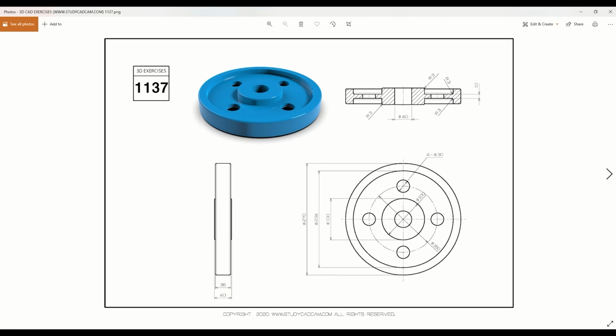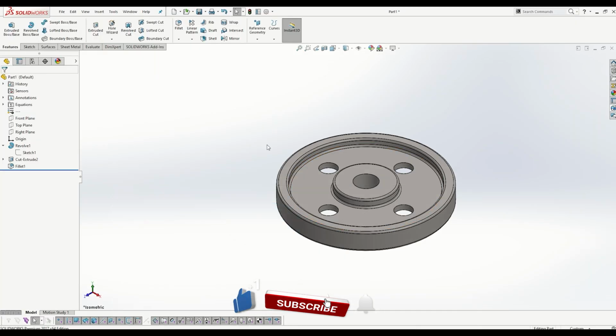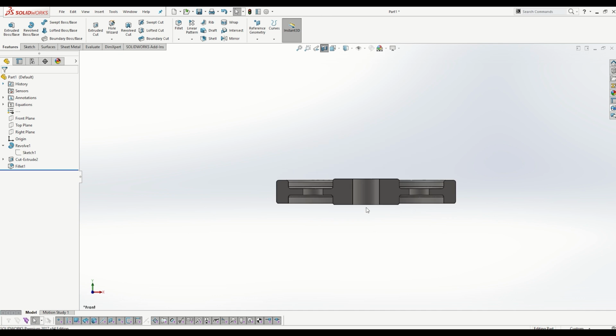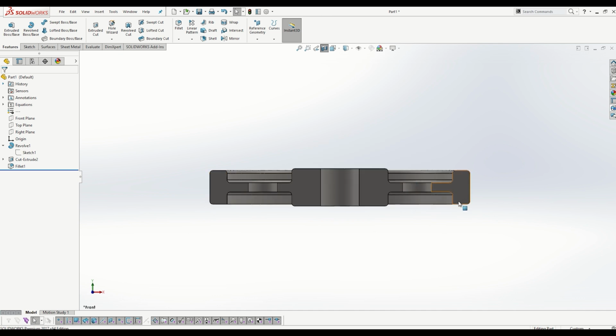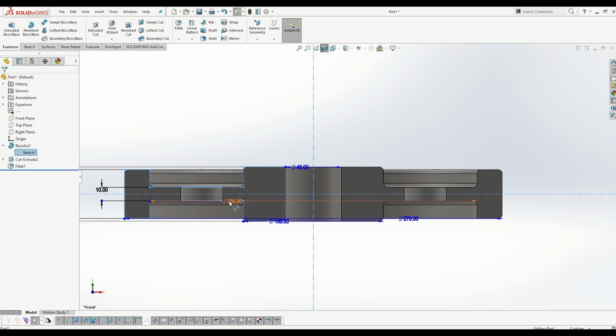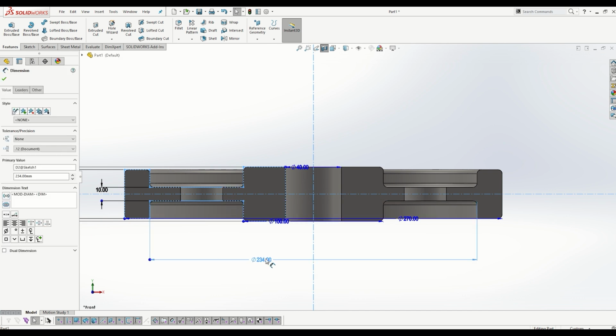The same thing, how to verify the cross section of your model against the given sheet. The given section view, right? You just section it to see whether it is exactly in the center or not. Go for a section, make it normal. The same thing will be replicated here. For dimensions you can't see them directly, you just click it and it shows the dimension. So this is the option to verify your sketch.